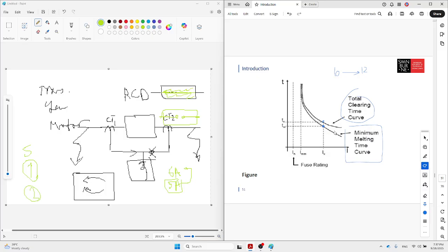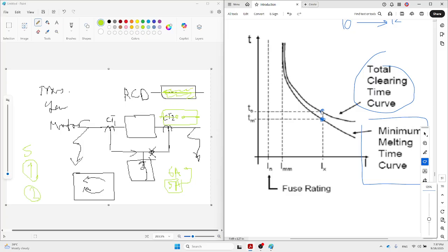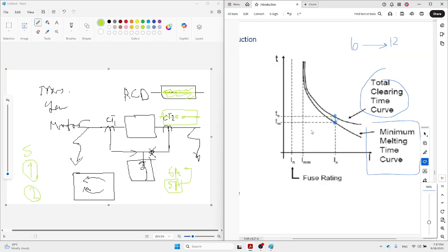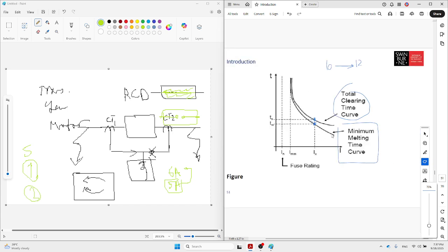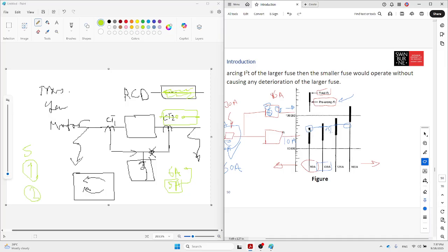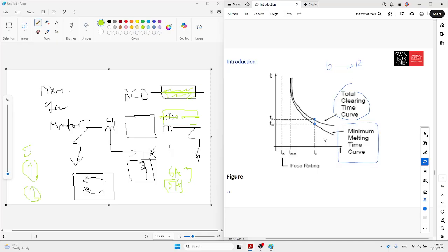You can see this curve. Maybe you'd say it is not a big difference, but in the case of protection, it's very, very big. You can see this difference is a big one. So the times Tm and Tc are totally different. When we choose something for coordinating based on Tm and Tc, something like this happens. So Tm and Tc are the most important. Usually we don't refer to Tm and Tc, okay? We usually mention the time of operation for the relay.